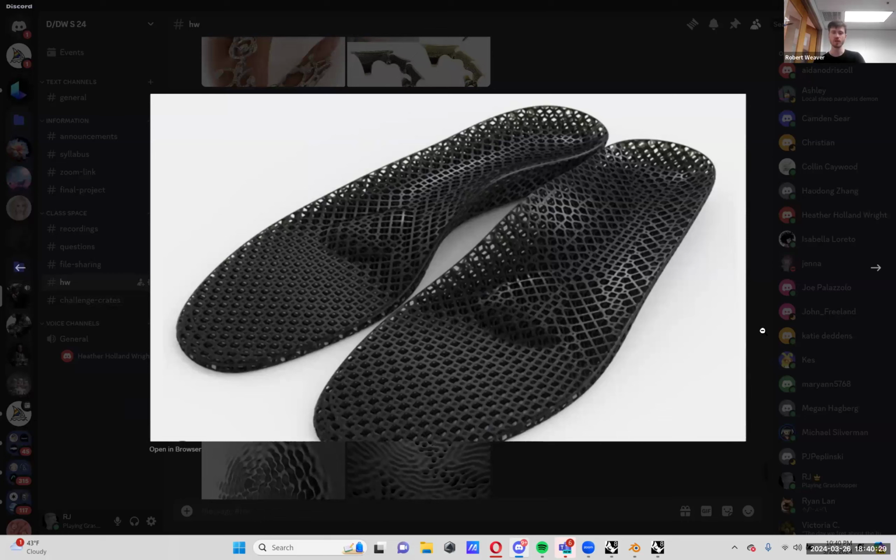Yeah, if you're going the crystalline route, the way it works is it likes to tween between surfaces. So if you have the surface of the shape flat and then a surface molded to the foot, you can set those two surfaces and tell crystalline to put 3, 4, 5 layers in between, and it'll make the grid pattern for you.